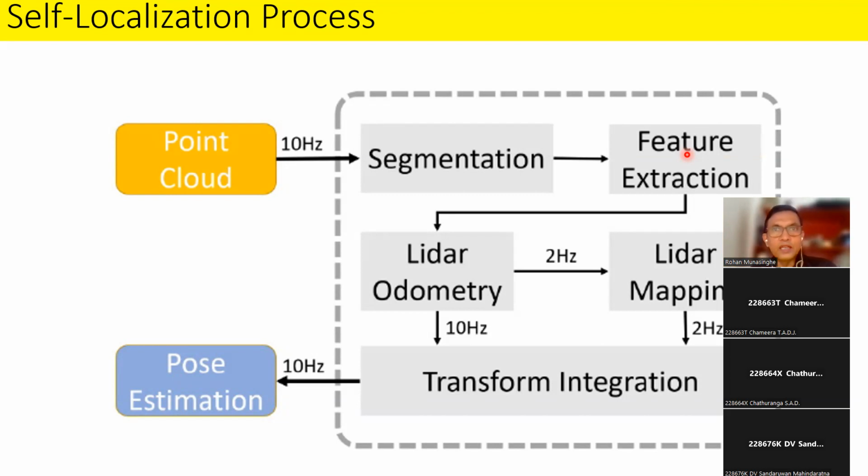But next time when you come to that point later on, the vehicle is probably not there. In that case, it doesn't understand what it is, but there's no harm. But if there is another new vehicle coming as the robot moves, that was not there when the map was built, then the robot is in great trouble. How to deal with it? Immediately the robot has to take the scans and identify that there is a new object here. The robot doesn't know whether it's a new object or a static object, or maybe the robot is in a different position, not actually the position it thinks it is now. So all sorts of uncertainties come into the picture.